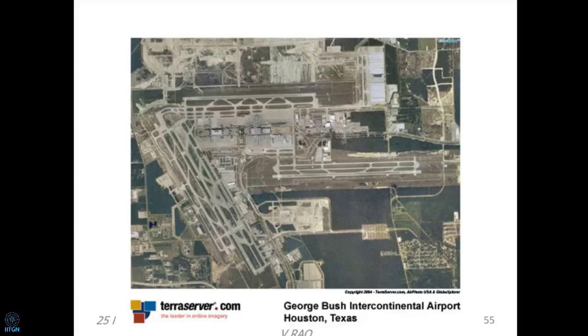So you should be able to exit very fast. If you exit very fast, we need the taxiway at a smaller inclination. That's where you can take a turn at 120 kph also. So these high-speed taxiways ensure that the runway is used by a single aircraft departing or landing for minimum time.